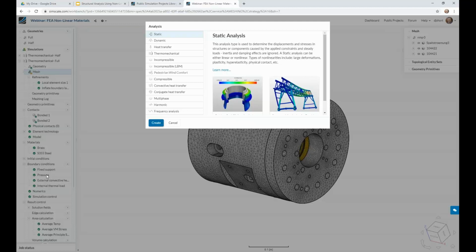So that wouldn't necessarily be a thermomechanical simulation type, but you could do that, for example, in a heat transfer unit or a cooling system where we would simulate the thermal behavior of both the fluid and the structure using a conjugate heat transfer simulation. We could then take those temperatures as surface averages and bring them into a thermomechanical FEA simulation, and you could do all of that in the same project. Under here we could add a conjugate heat transfer, and then add another thermomechanical simulation, and then you'd have the full feedback for your structure. You're going to not only see the fluid behavior and the temperatures in the fluids and on the structures, but also the mechanical stresses induced by those temperatures on the structure itself.